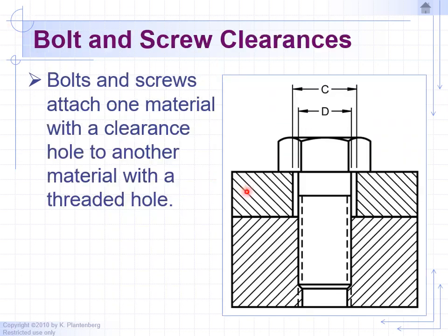Okay, in this example, we are attaching this plate to this one. So notice they have a different hatching pattern. This hatching pattern is the same as this one, and it should be because this is one plate. And then we have a different pattern for the lower part. So this is a separate, let's say, block of aluminum. And this, let's call this one also aluminum. And we're bolting them down together or clamping them together.